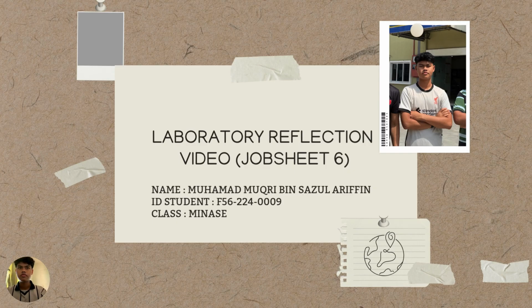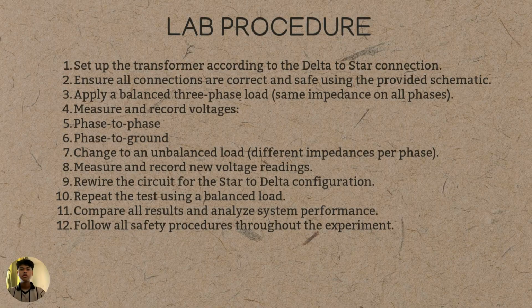Today I want to present my job sheet C. Okay, first of all, I want to give my lab procedure. First, set up the transformer according to the delta to star connection. And ensure all connections are correct and safe using the provided schematic.